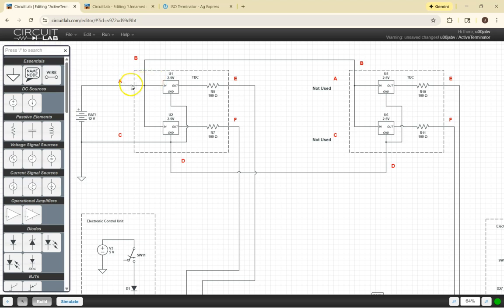So we can see that through terminal A, there is internally, and you can measure this with an ohm meter, continuity between A and B and between C and D. This is basically just a jumper that is contained within. I don't know if it's physically a jumper, but there is a connection between pin A and pin B that does not require any logic or any electronics. It's just a physical connection. So whenever I plug this device in, whatever I have on terminal A goes to terminal B, so I'd have 12 volts here. That provides the 12 volts over here at terminal B.